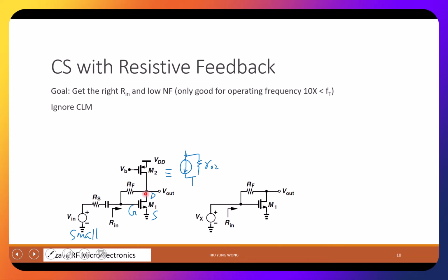Because this might be 1 volt, and then you cannot add a plus minus 0.2 volt to 1 volt if you don't have the capacitor, right? Because you're going to short it. But with a capacitor, the DC part is separated, but the AC part doesn't see the capacitor. You just go through, right? So we did not have time to talk about this, but I spent a lot of time in E122 to talk about the meaning of small signal and DC bias, right? We talked about why we need this coupling, right? So now just take it for granted.